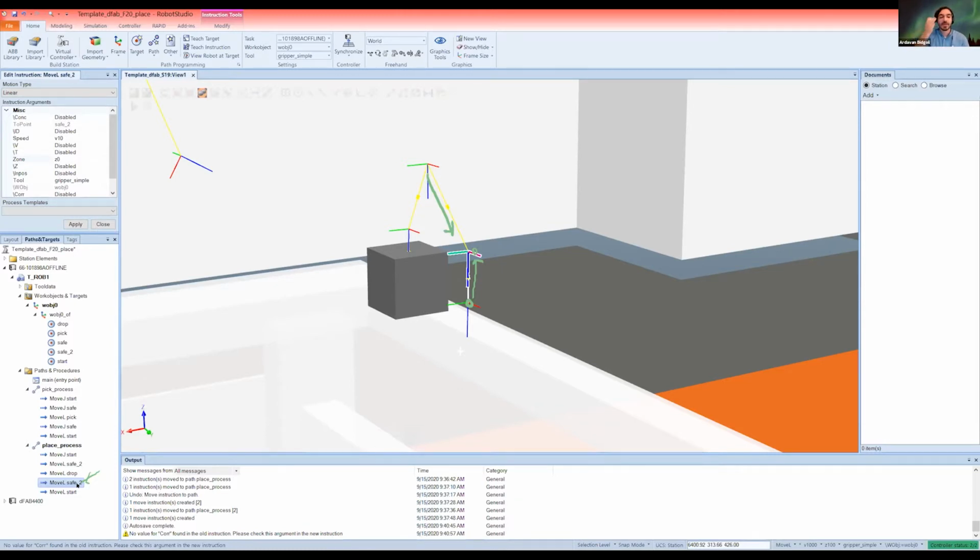The reason is that, for example, imagine that you are trying to put something inside something else. So let me just think about what do I have around here that I can demo this. So this is a lens hood. This is a lens. So imagine that this is the place that you want to put this lens inside of it. So the target here, and this is the safe place, okay? And I know that I put the hood upside down. But imagine that I go down here and put this thing here, okay? This is definitely move L because I don't want to make a motion like this, anything other than linear. So I move linearly inside, and then I go all the way in.